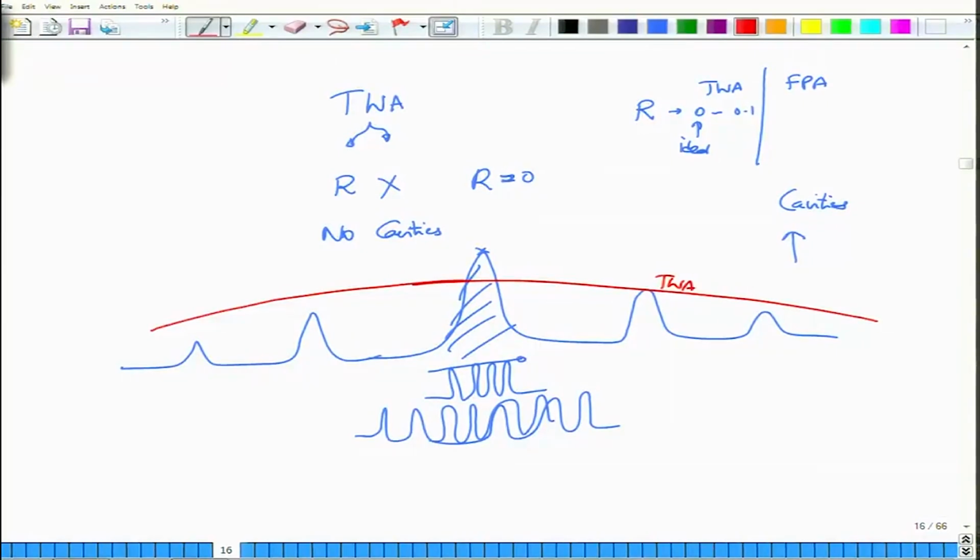Okay. So you have to of course improve the single pass gain, because that is exactly equal to the gain of a travelling wave amplifier, by continuously increasing gamma, increasing g, and then reducing this alpha and increasing L. So this has to be increasing, this has to be increasing, loss has to be reducing, and L has to be increasing, all with certain constraints and approximations.